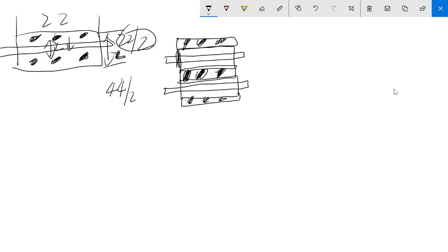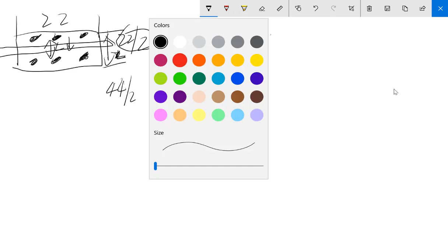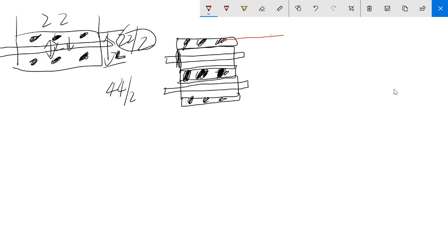If we short these two together, because they are sharing the same metal 1 to P plus contact, and these are the two gates, right? The way to do that is, imagine that we have a metal here and a metal here, and we short them together, and then they combine to the middle, and here's the output. So this one, for example, is the source of the PMOS, okay?